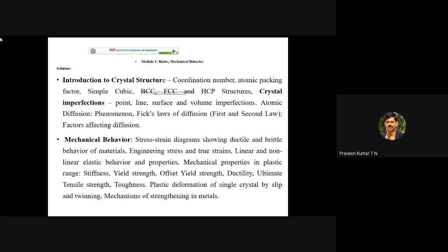But once you apply 4 kg of load, the dimension is different, and when you apply 5 kg of load, the dimension is different. So you have to consider the original length as the length in the previous stage of loading. That is a little bit difficult, especially for the true strain. Anyhow, we are going to do the derivation. But in general, at this moment, you should know that engineering stress is given by load divided by the original cross section area.